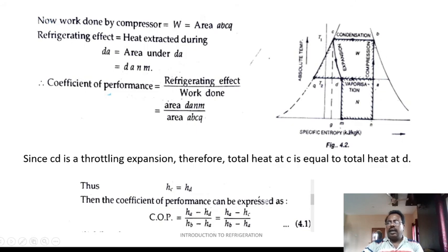So the conclusion of this is, why we are going to study this temperature entropy diagram for three conditions, that is for wet vapor, dry vapor and supersaturated vapor, is because we need the condition of the vapor after compression to be saturated vapor.